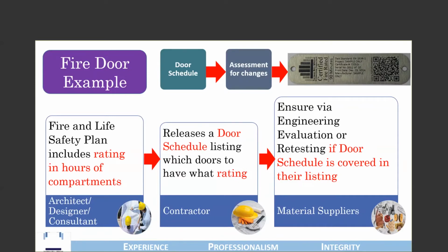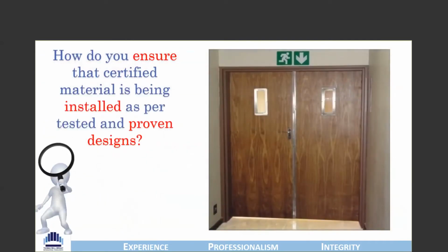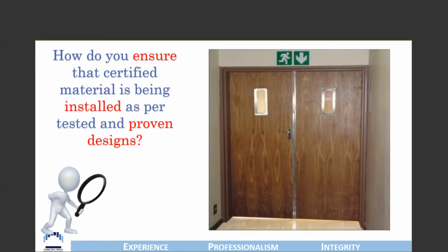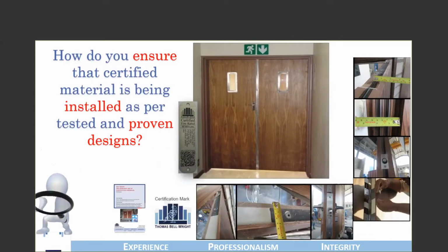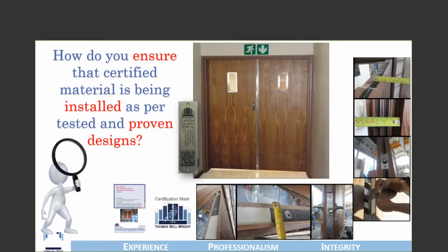So the tool of assessment provides an additional level of assurance to buyers of fire doors, and often certification bodies, compliance bodies go to an extent of issuing fire door labels which often capture enough information for the inspector at the construction site who is overseeing the installation to check what is the link between the doors that were tested or assessed to perform in a certain way and the doors which have reached the construction site.